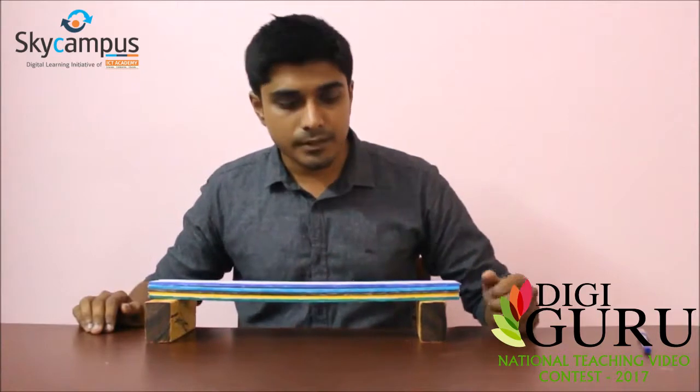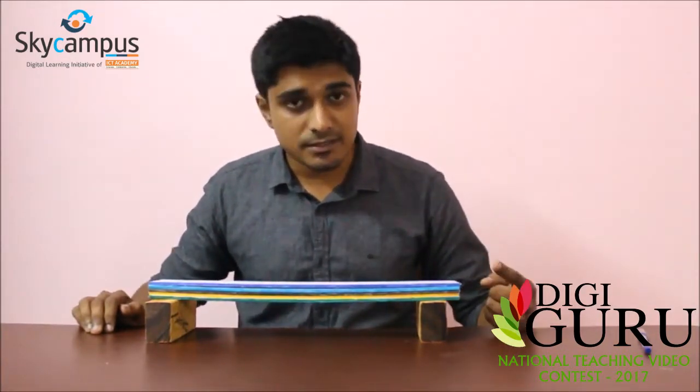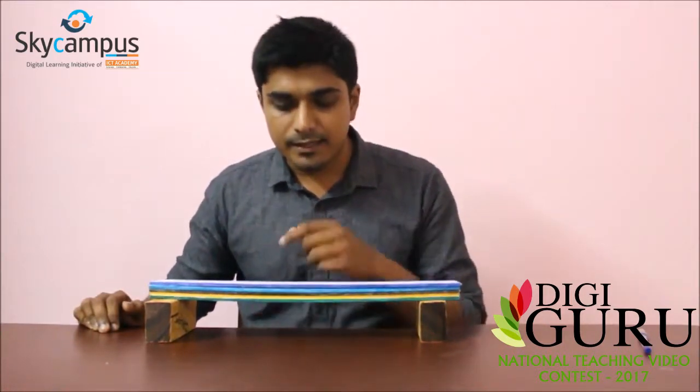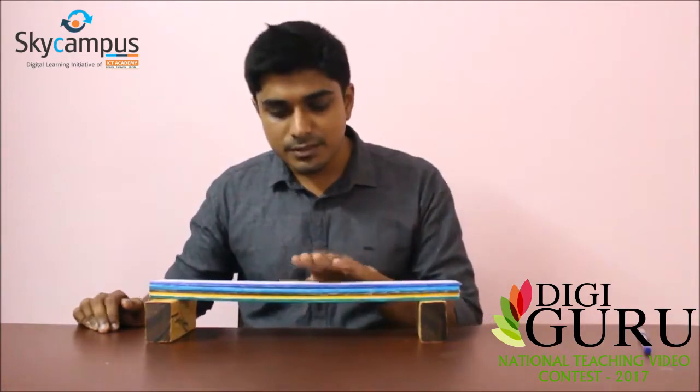So in conclusion, we have two types of stresses developing in the beam as it bends. One is the direct stress or the bending stress, and the second one is the shear stress. Now the bending stress is maximum at the topmost and the bottommost layer of the beam, and it gradually goes down to zero at the neutral layer. But in case of shear stress, we have zero shear stress at the topmost and the bottommost layers, and then it increases to the maximum at the neutral layer.